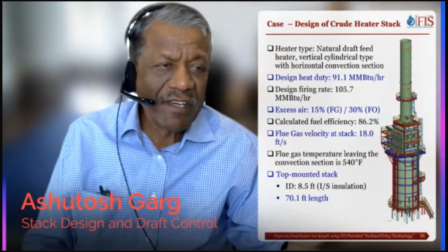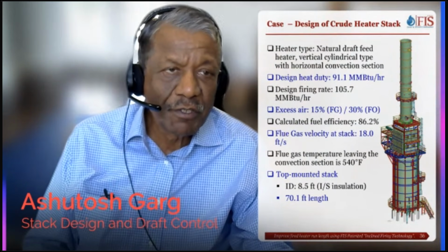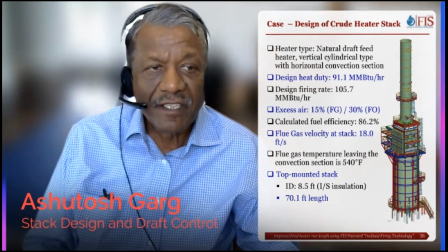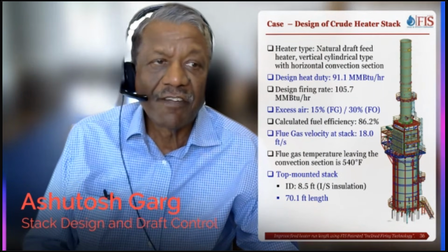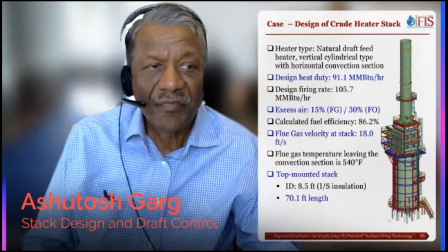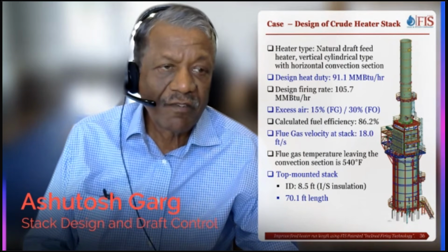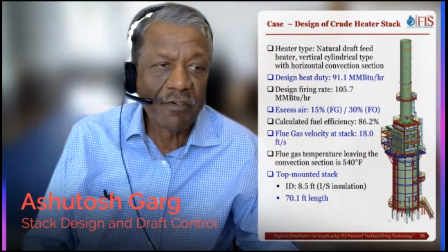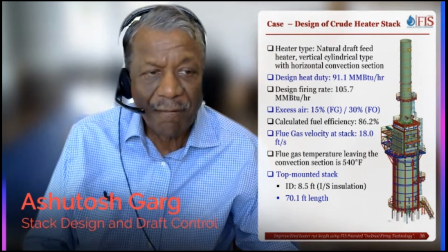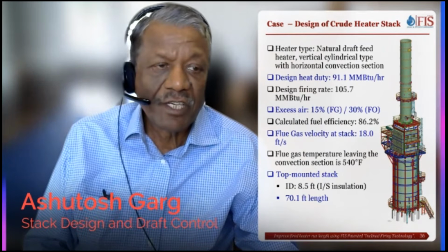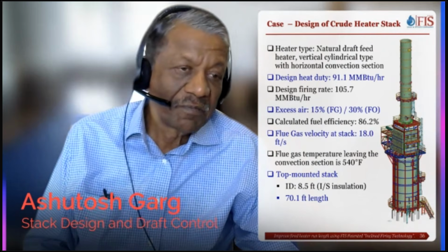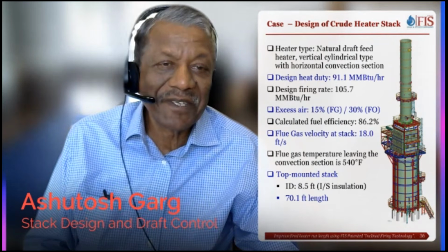So we do have a case here. I want to show it to you. We have a case for a real project. The design heat duty is about 91 million BTUs. This heater was burning fuel gas and fuel oil. Efficiency is about 86%. Flue gas temperature leaving is about 540 degrees. My team has already given you the answer over here.